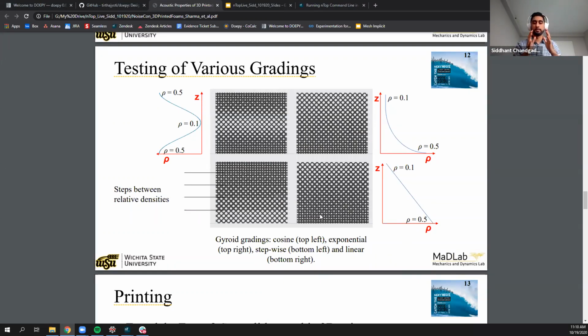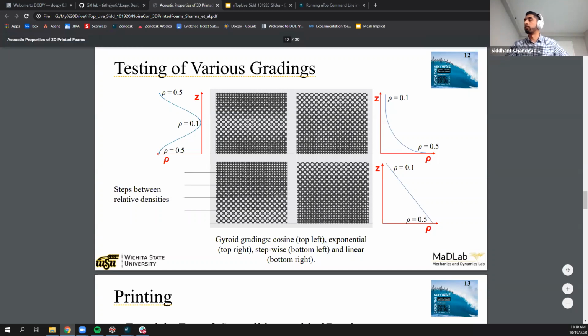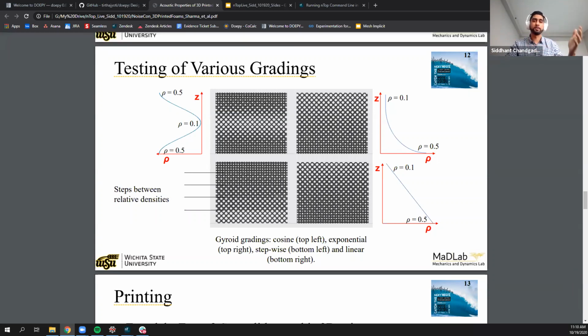The notion of modal analysis is that we can obtain the natural frequencies and the mode shapes of certain structures in certain environments, whether they be free modal analysis with no restrictions or restricted by however many restrictions you want to include.